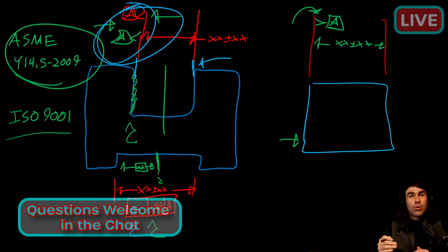They're not totally different things, but ISO 9000, 9001, it's like bookkeeping standards. You could use those and ASME for your drawing. So if you're in Europe or outside the US, maybe look at ISO GPS, but you're not going to get as much support for that as you would for ASME, for free on the internet, right now. I doubt anybody is doing an ISO GPS live stream. Maybe, I don't know. If they are, let me know. That'd be interesting.